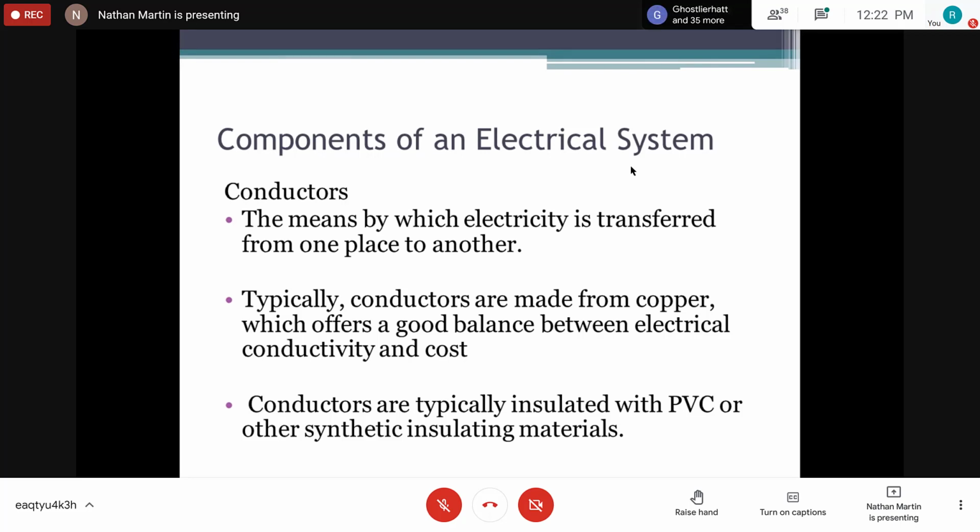So it's a triplex, and it's typically used for 220 single phase, 3-wire situations where we have 2 phases and a neutral conductor. All right, and they come in various sizes depending on your design current, guys.